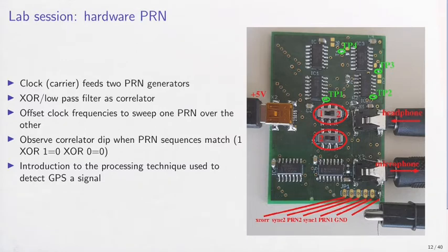Gold codes are pseudo-random sequences 1023 bits long, published by the US Air Force, and used in GPS receivers to have a local copy of the sequence and have an accurate timing capability. We will not get into the fancy Gold codes. We will make it very simple, and show how easy it is to create this pseudo-random sequence using linear feedback shift registers and XOR functions, and by watching how these two pseudo-random sequences will correlate if they match and not correlate if they do not match.